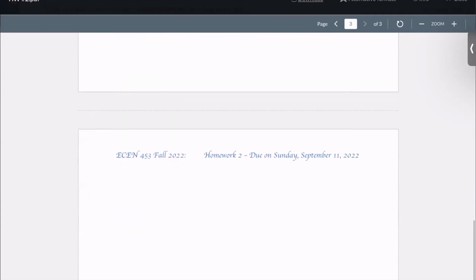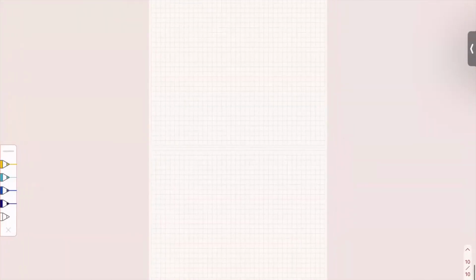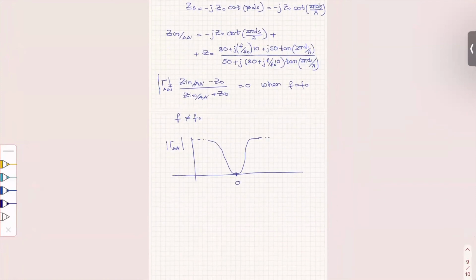Okay, so practically what I want you to find on the computer is this is the max, this is 0, gamma max, and then I want to find the points where that becomes half of the maximum value. I mean, it could be anything else, all right? So these two points. And then we say that the reflection coefficient is smaller than that, and you can define it as somewhere of the bandwidth.